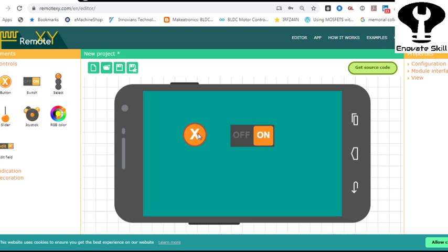So each and every thing you can reconfigure. For that, you have to change a few configurations of the Bluetooth, meaning you have to put it in AT command mode, and then after entering AT command mode, only then will you be able to change these configurations. For that, I will upload one dedicated video on this YouTube channel in the upcoming one or two days.